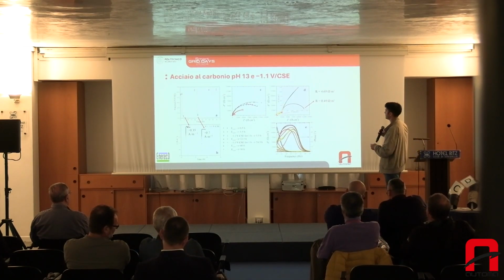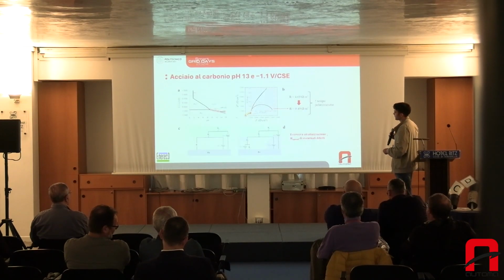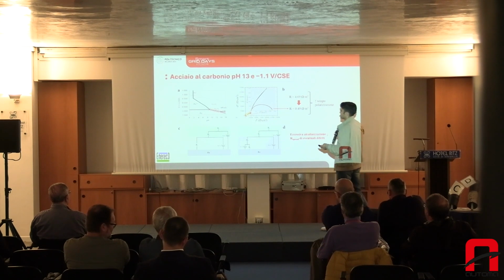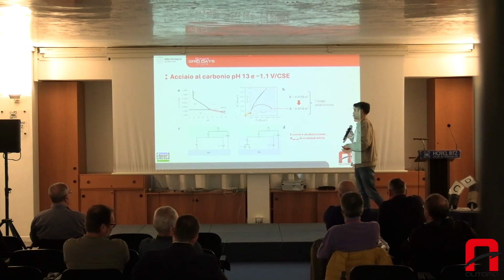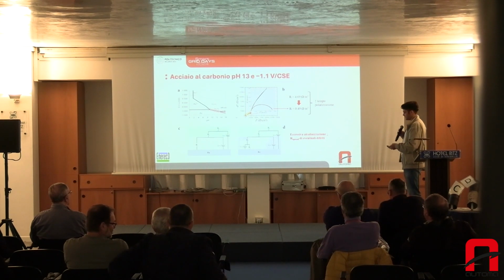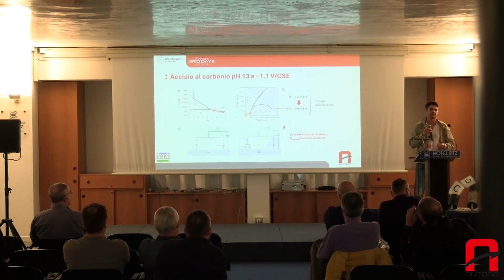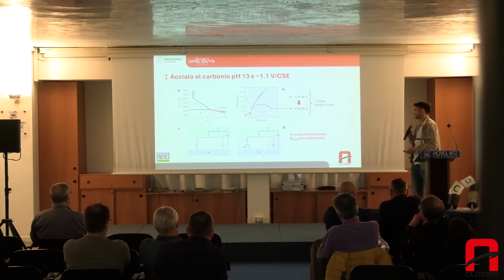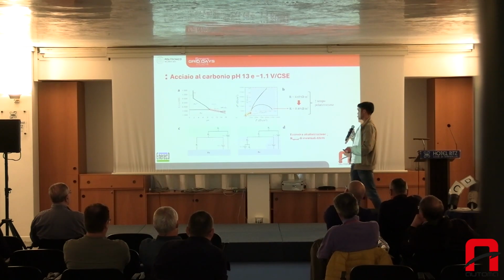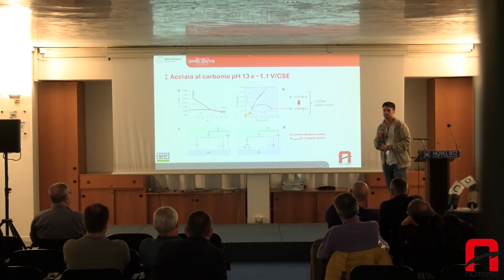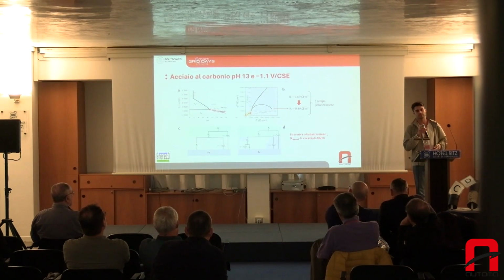These are the polarization resistances that get developed, and as you can see, the values are quite low. After a number of polarizations, the alkalinization process changes the oxides that are developed on our material. In particular, the oxides are made up by a number of stages, and these stages are less protective. So if there are defects on the coatings, we expect a spread resistance which is low, which is assumedly low.